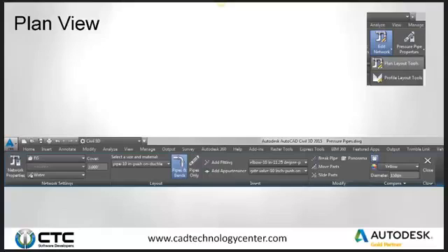Select size and material. Again, it's picking a 10-inch ductile iron pipe. I got pipes and bends, pipes only. So anytime I do pipes and bends, it will continue my line on. Pipes only, it stops. Now I have add fitting, add appurtenances, just like I did in profile view. I have break pipe, move parts, slide pipes.